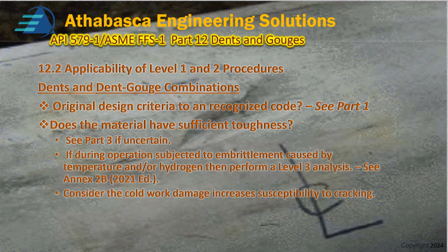Now you need to consider the fact that cold work damage increases susceptibility to cracking, because when you work harden the material by gouging it, you make that surface harder, and when it's harder, the ductility tends to drop for steels, and basically you can have more chance of cracking.